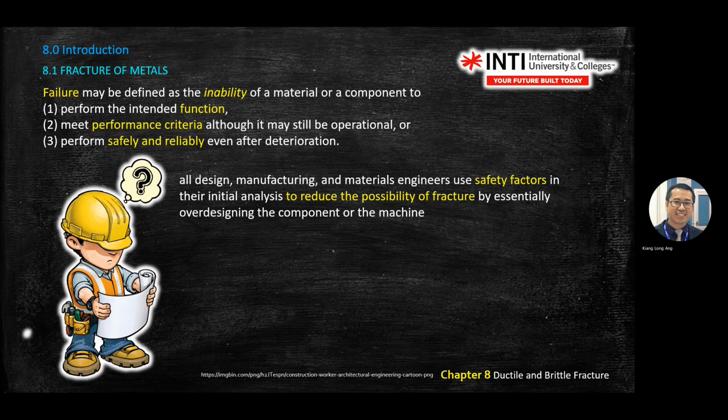Okay, so failure, a loss of definition. Failure means a fracture of metals, especially. It means the inability of the material or component to meet these three items. If the material is unable to perform its original function, it also falls under the failure definition, or it does not meet the performance criteria, although it may still be operable. So it means the inability of the component to meet performance criteria.